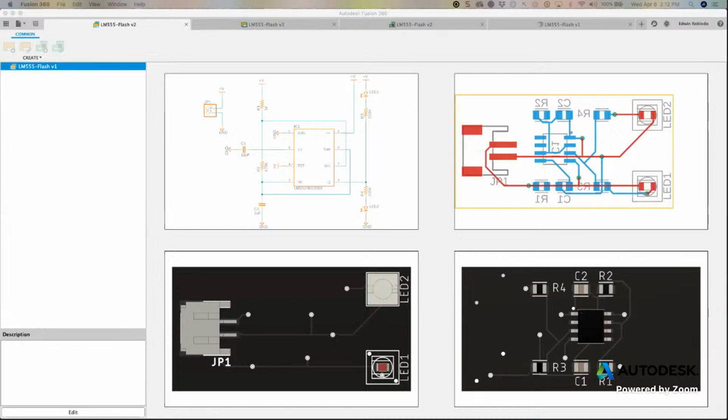Now, the topic today is about DRC, and I just wanted to go over this. It's not going to be a really long presentation. It will be kind of short because we just want to do an overview of the DRC. Now, the DRC stands for Design Rule Checker. In essence, it's the parameters in which you're going to be setting up your design. That way, you can make sure that it's actually manufacturable, that it actually works physically, and that all the geometry is not overlapping other geometry and so forth.